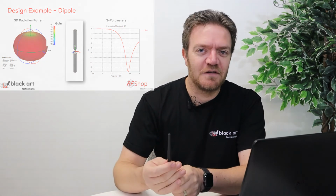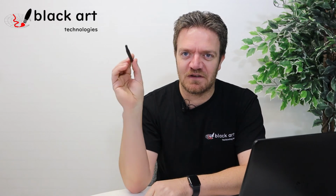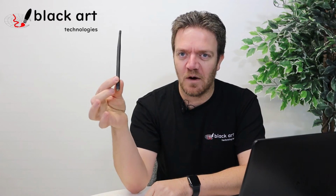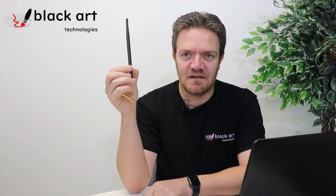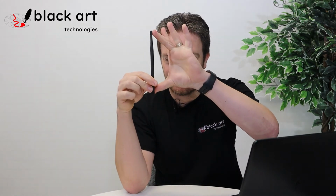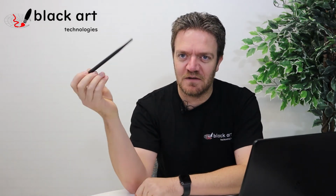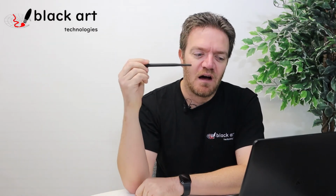So the first one is, I'm back on my dipole. This is the same dipole I showed earlier. So I just have a 2.4 gig dipole. A dipole is an antenna that has two quarter wavelengths and it's fed in the middle. It creates a resonance. Now this is obviously inside the radome, so the antenna in here is much smaller than what you actually have. I use a tool.